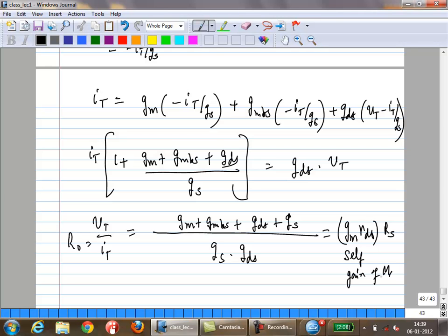Okay. So this is the overall output impedance. The output impedance of a normal transistor is just RDS. So now this is actually larger. It's GM RS times RDS. That is one way to look at it. The other way is the next structure we're going to look at, which is what happens if you replace this resistance by another transistor. Okay?